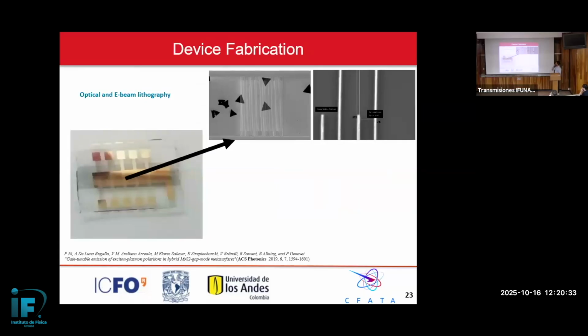Okay, so we went to the clean rooms. What I am actually showing you here is a picture from a cell phone of the device. This is 1 centimeter by 1 centimeter. We have large contacts to electrically access the semiconductor, and the stripes are like 17 nanometers thick, and the separation is about 375 nanometers, in order to match the simulations. So this is like a Dorito in the jail, right?